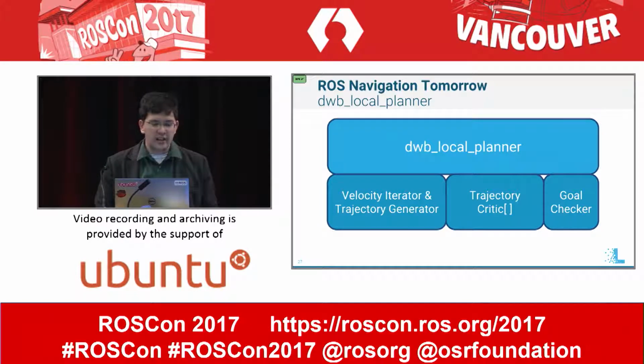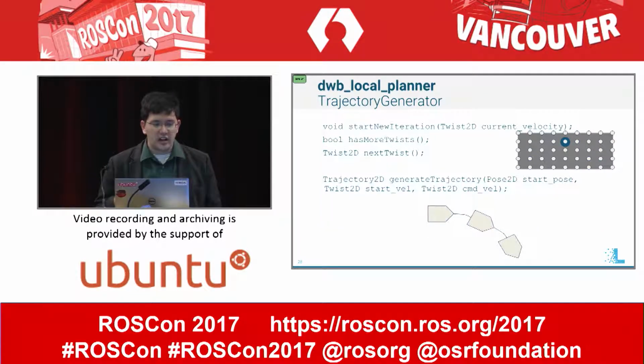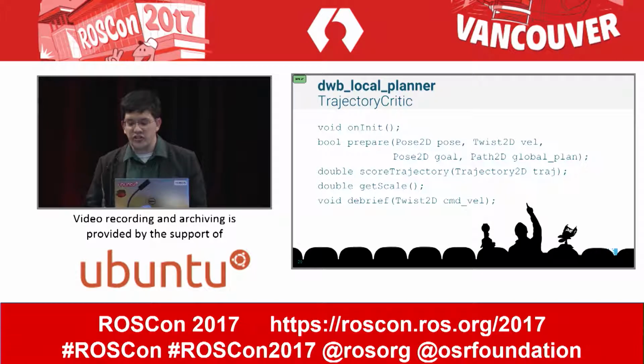And so in that first bit, we have the trajectory generation. So we have a standard iterator interface for iterating through the different velocities, and you feed in the current velocity there. We have the function for generating the trajectory that takes the start pose, start velocity, and command velocity. And then we have all the trajectory critics, people, or things, that will critique the trajectories.